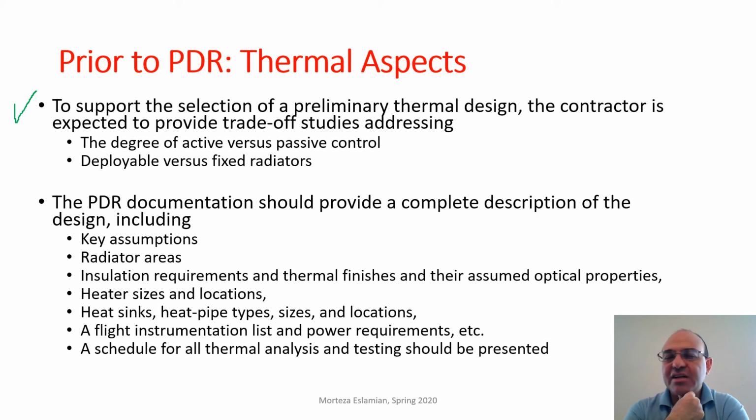Now, if the contractor wants to use active systems, like a mechanically pumped fluid loop instead of heat pipes, then they need to provide trade-off studies to demonstrate the need for more complex active systems instead of simpler, usually cheaper, passive control systems.